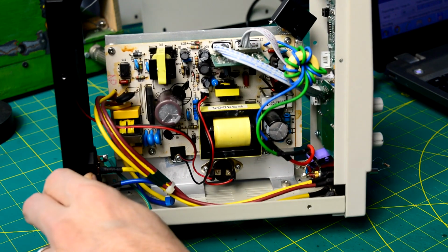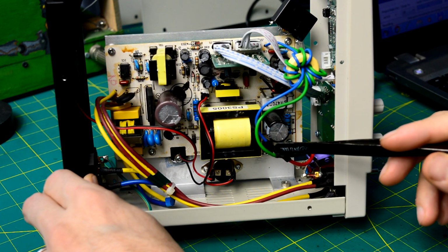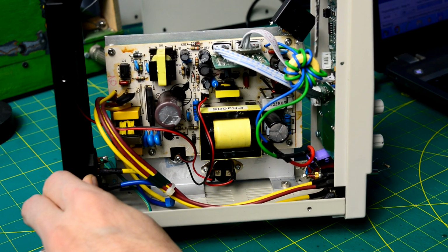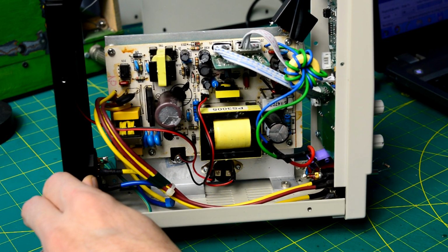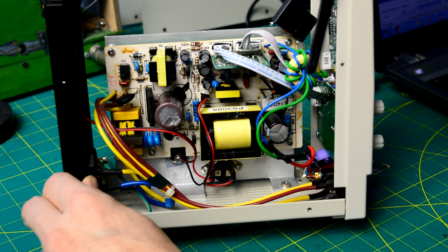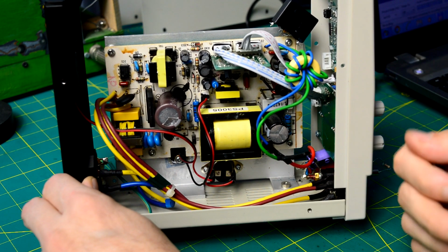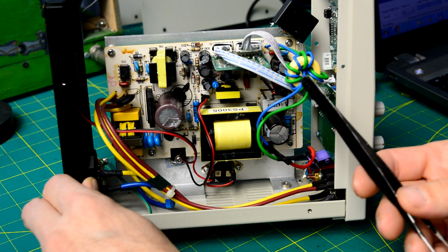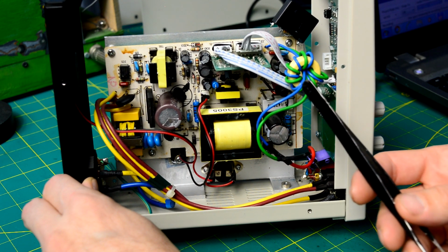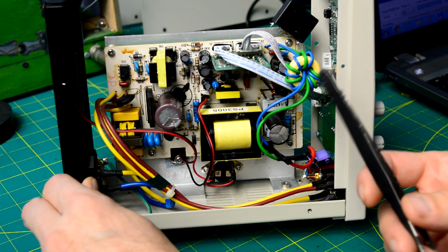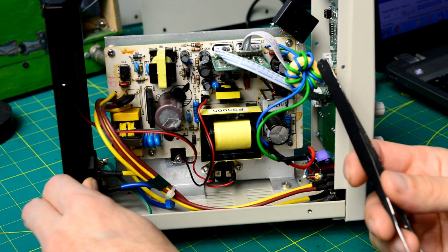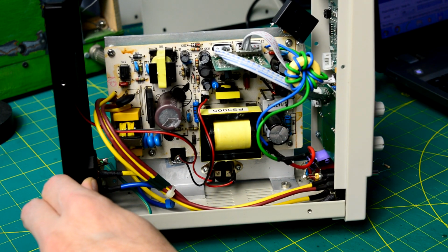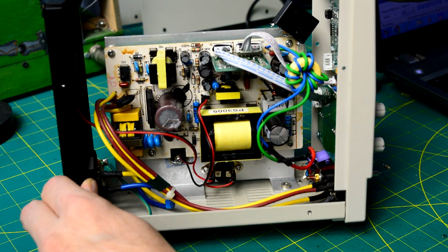What I did was extend the supply lines, from the board to the connectors, and add this ferrite ring. I wound the supply lines around this ferrite ring a few times to create a basic common mode choke. So I added inductance on both wires, both the plus and the minus, and by putting them on the same piece of ferrite created the common mode choke. Now let's see if this actually helps.